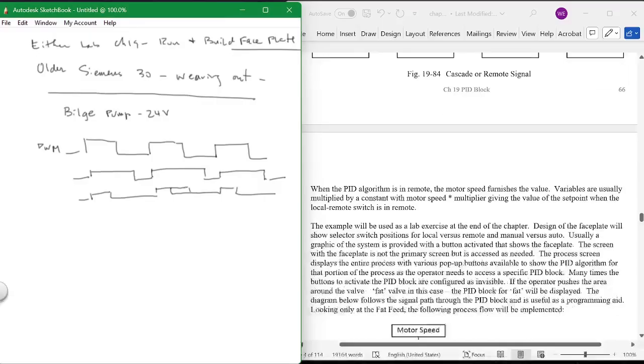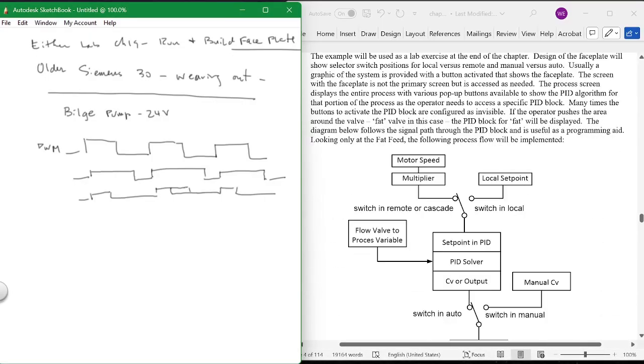What happens to the integral of the error? It gets bigger and bigger and bigger and bigger. Now, when that rag flushes through, what happens to that valve? It takes forever for that integral of the error term to come back to 0. It takes forever. So what do you typically want to do?